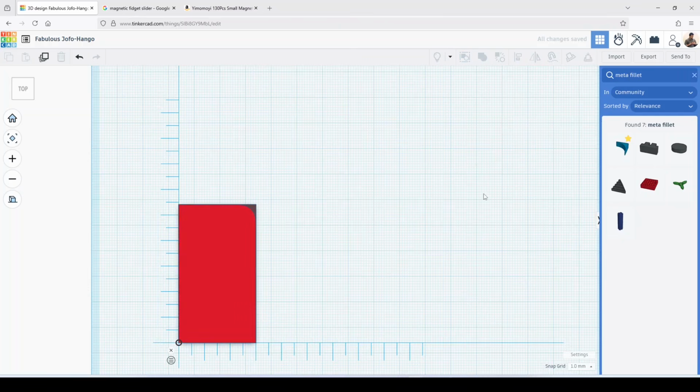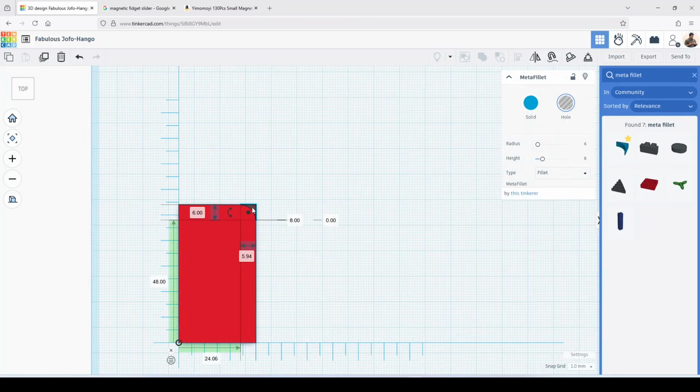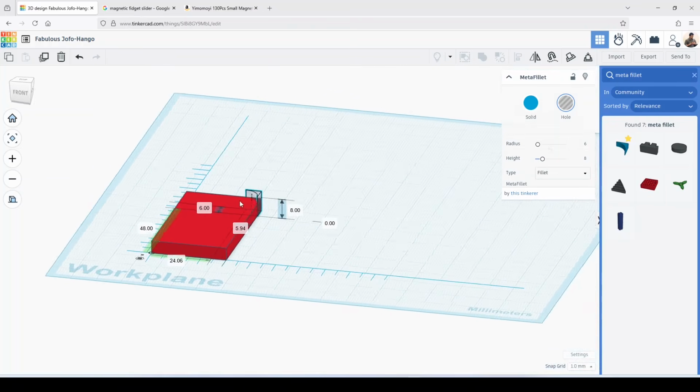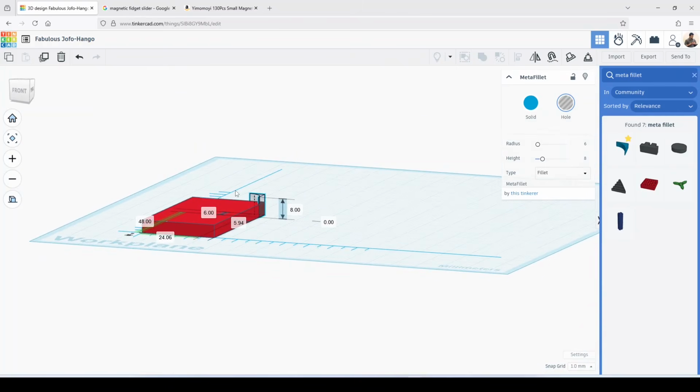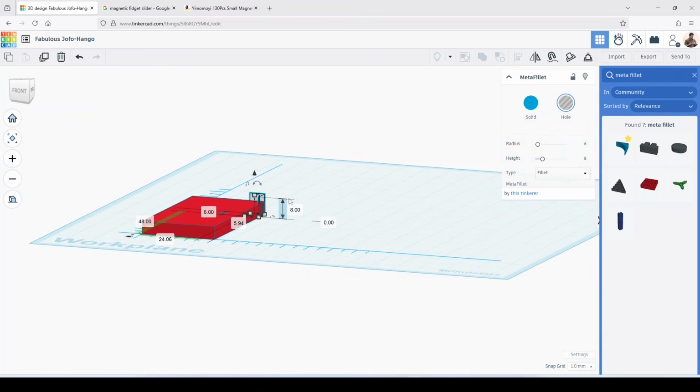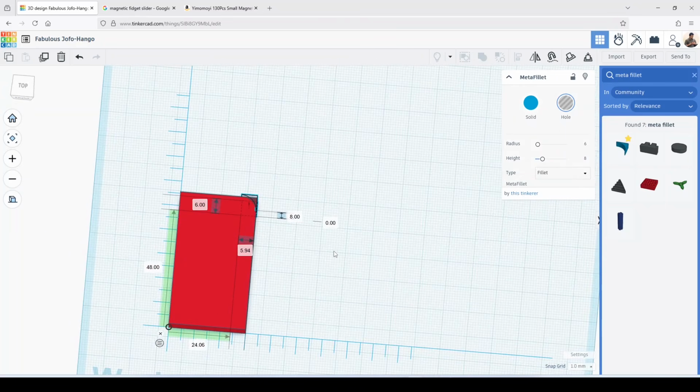And if it's grayed out, it's already aligned. So this will guarantee that you're actually putting it in the right spot. If you want to be extra sure, you can tilt it a little bit, right click and drag. You can see that the hole, the fillet, is actually taller than your box, which is important because otherwise you won't be getting what we want in just a bit.